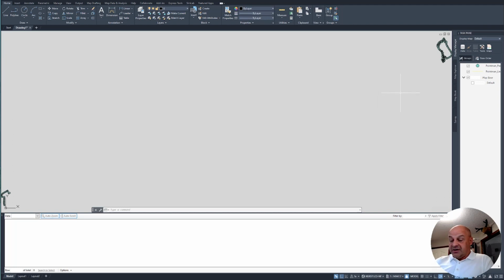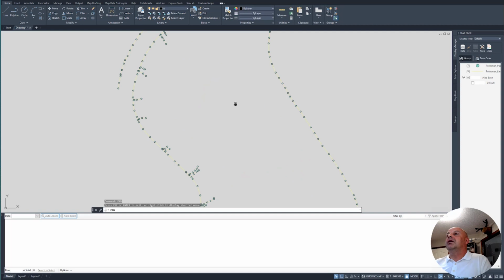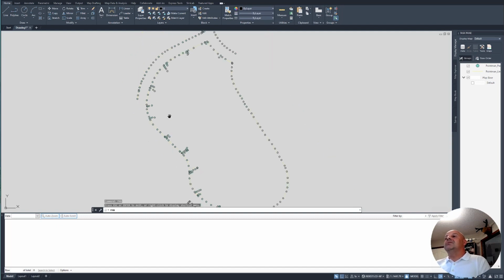Now let's move over to that so I can see it a little better. And over to it, zoom in, for example here. So these points are your pedigree, and the lines are just below them here. You notice it's all the same color because I haven't applied a style to it yet. Shapefiles, unfortunately, do not carry style information within them. That is an Esri limitation.